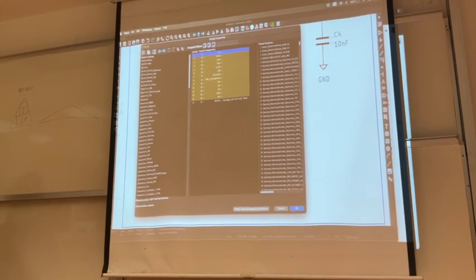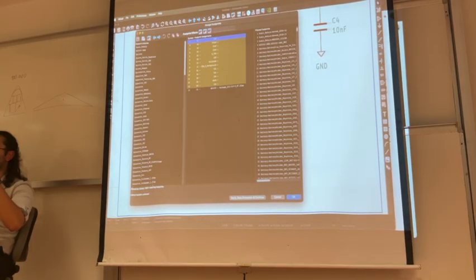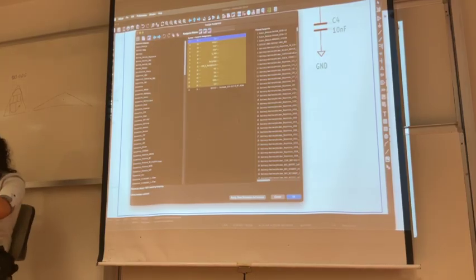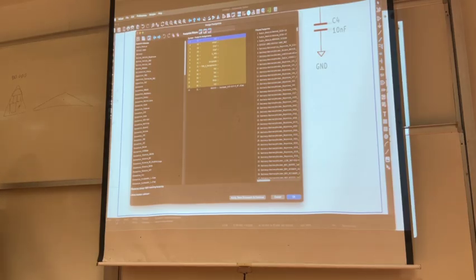So, I'm going to explain some of the things. We have a section called packaging. So, packaging tells you which footprint to use. Footprint is the part that you connect your component to the PCB, the part that you solder to. You can pick SMD components, TH components. We're going to place SMD components first.